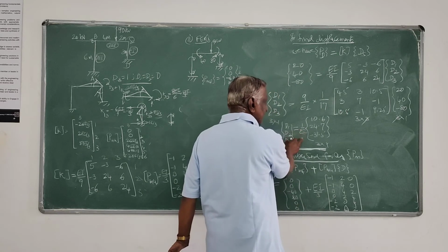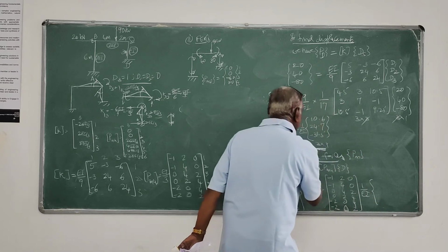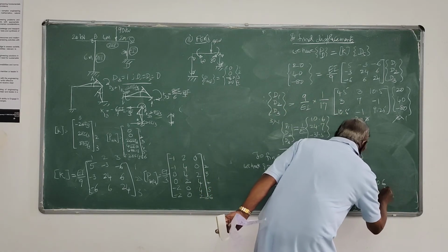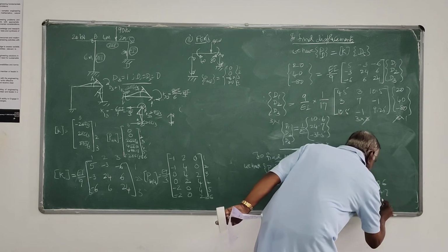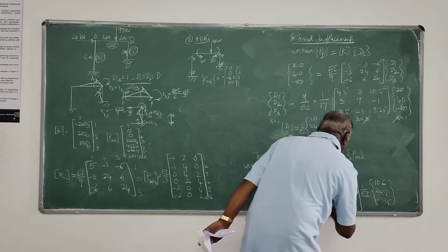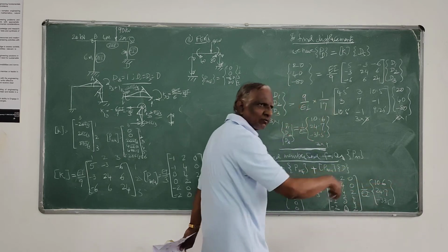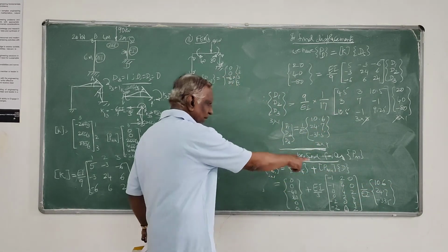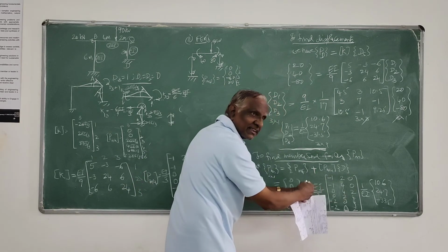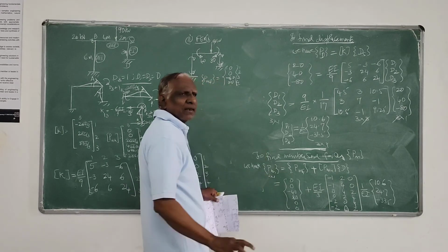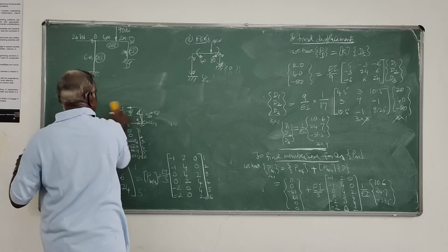D you have worked out just now, that is 1 over EI into 10.6, then 24.7, minus 33.5. Now we can multiply these two, because this is a 6 by 3 matrix, this is 3 by 1. That 3 gets cancelled, 6 by 1 you have to get. This is also 6 by 1. You can add the two matrices PMF, you will get PM. That's a very simple, straightforward thing that we will complete.